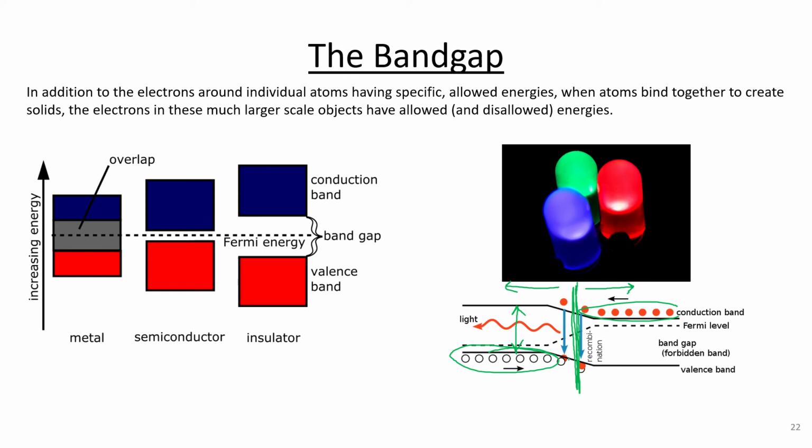And when they are brought together, when you apply a sufficient voltage to these, so electrical energy to these, then the electrons and the holes, because they're oppositely charged, are attracted to one another and they tend to recombine. And when they recombine, then it kicks out, as the diagram kind of implies, photons of light at a specific energy that matches the gap between the energy of the hole and the energy of the electron, between the conduction and the valence band in these materials.